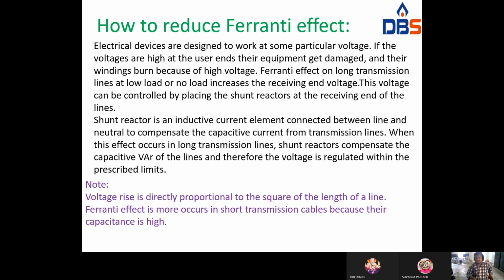So when the receiving end voltage increases, what happens if high voltage comes at the consumer? The equipment may burn. To reduce that, a shunt reactor is connected at the end of the transmission line, right? Because by using a shunt reactor we can reduce the Ferranti effect.